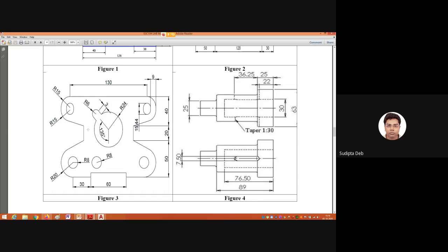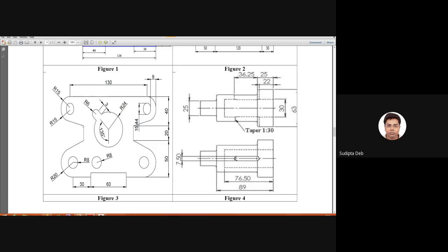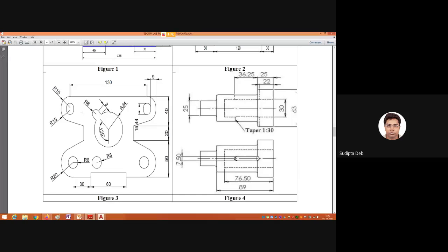Another thing I want to mention is, if we consider this line and this is the point, from here we have to draw, because it looks like a semicircular section. It is not semicircular. Actually, this line is the tangent drawn from this point to this circle. So here you will get one circle, because the radius is 15. You will draw one total complete circle. Then from this point you will draw the tangent.